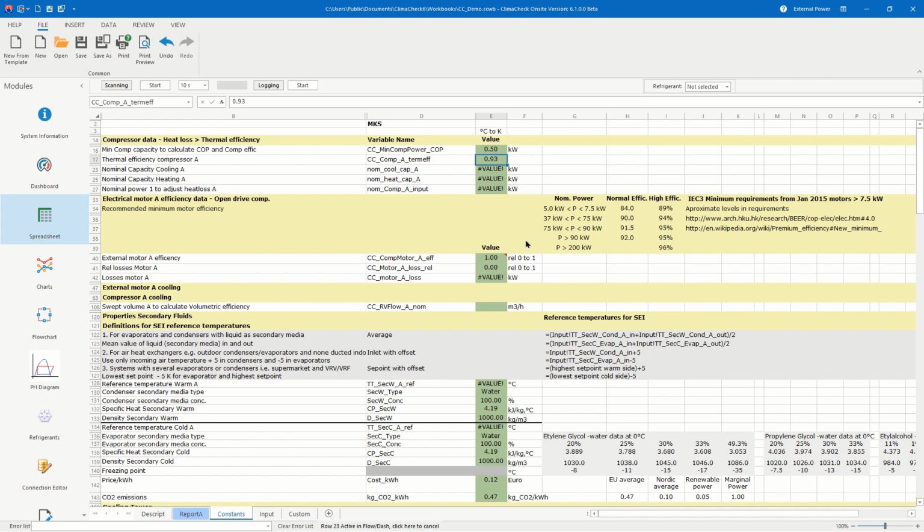to adjust this constant you need to first shield the compressor from this draft or turn off the top mounted fan. Start a measurement and take note of the compressor efficiency, and then remove this shield from the compressor, and then you adjust the thermal efficiency until you get the earlier noted number. And if you have an open drive compressor, you need to change this efficiency.